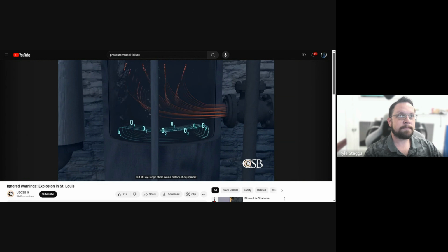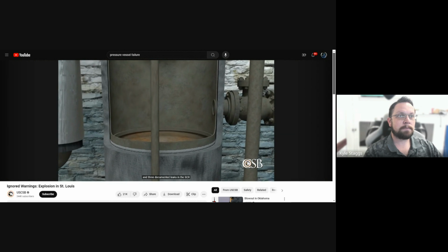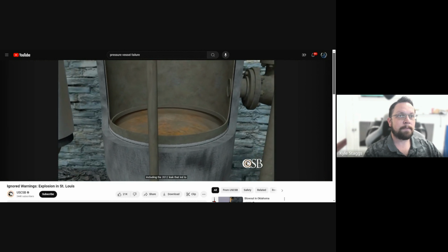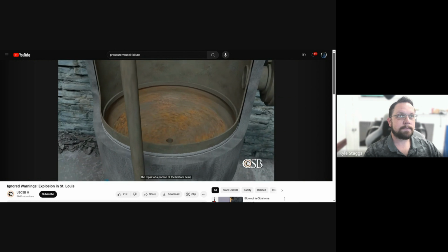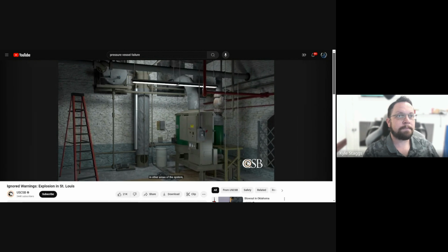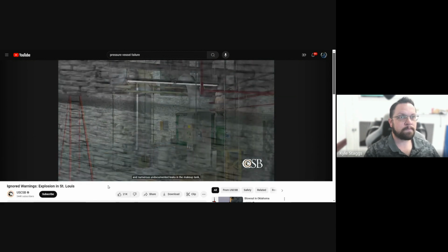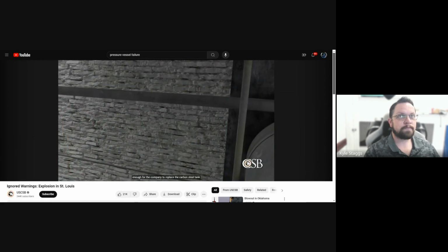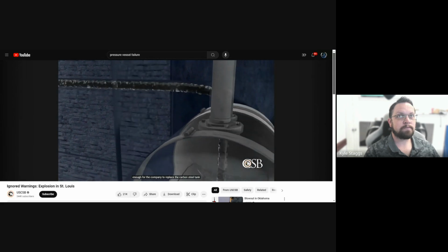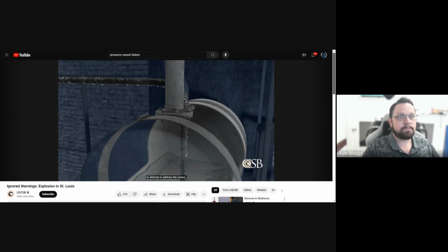But at Loy Lang, there was a history of equipment failures caused by oxygen corrosion in the steam system: 3 documented leaks in the SCR, including the 2012 leak that led to the repair of a portion of the bottom head; 5 documented corrosion failures in other areas of the system; and numerous undocumented leaks in the makeup tank, enough for the company to replace the carbon steel tank with one made from stainless steel to attempt to address the issues.